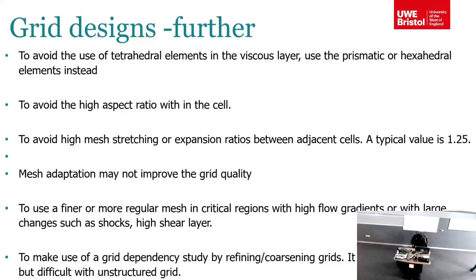So don't use tets near the boundary layer. Use prismatic or hexahedral elements. You have to avoid high aspect ratio cells. Don't have large stretching ratios or expansion ratios between adjacent cells.